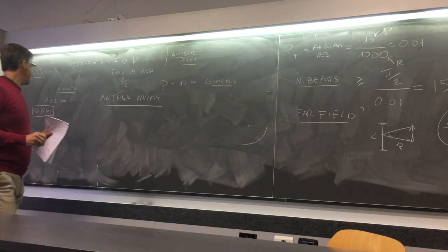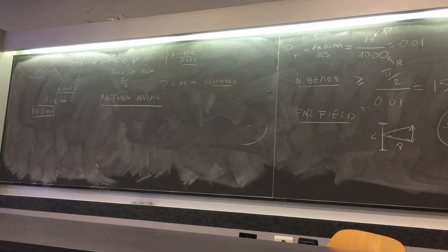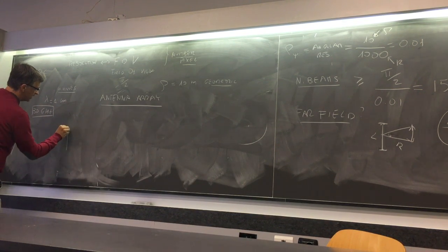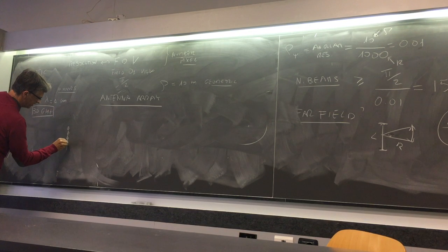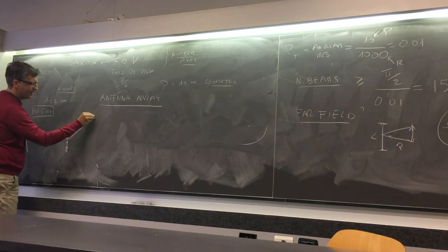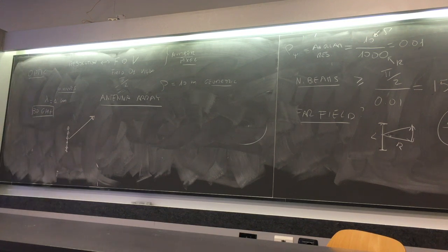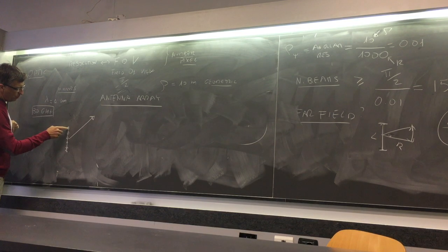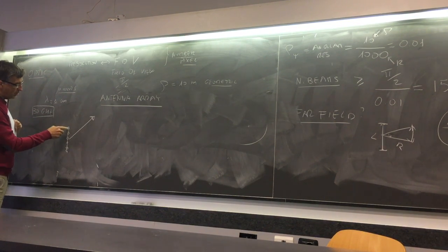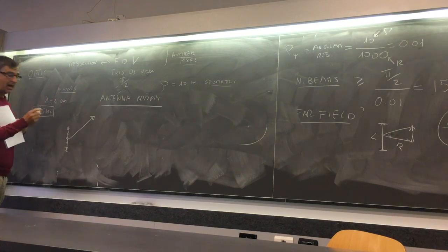The antenna array is a much better configuration because we don't need to make any rotation. Or let us say, you remember, if we want to have a beam looking in that direction, we just need to make some coefficient here in order to have a proper phase.